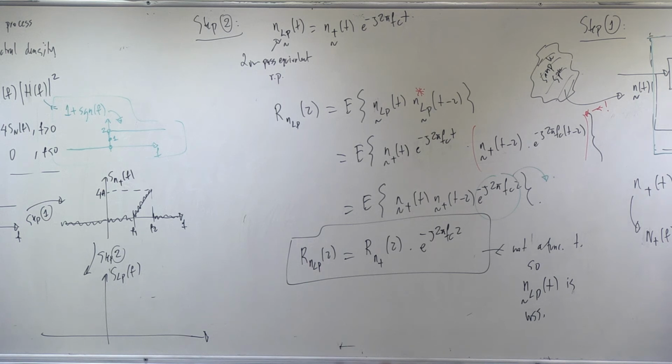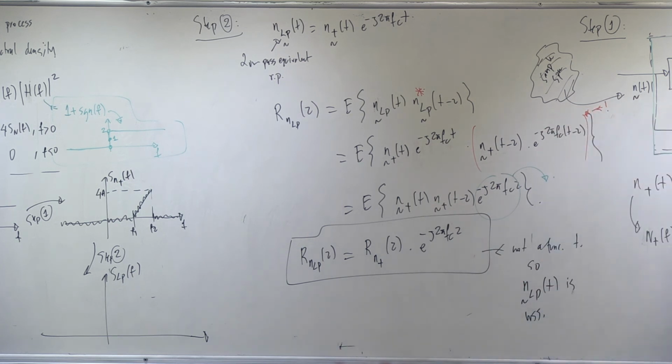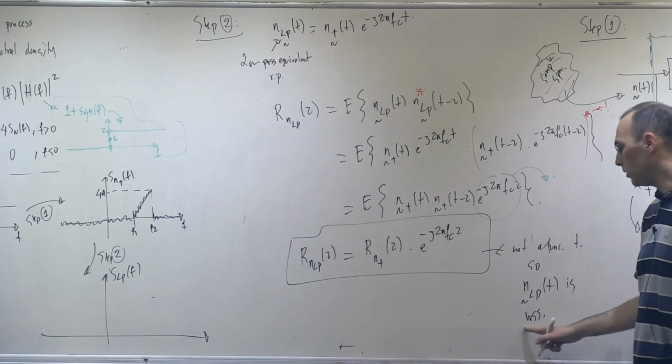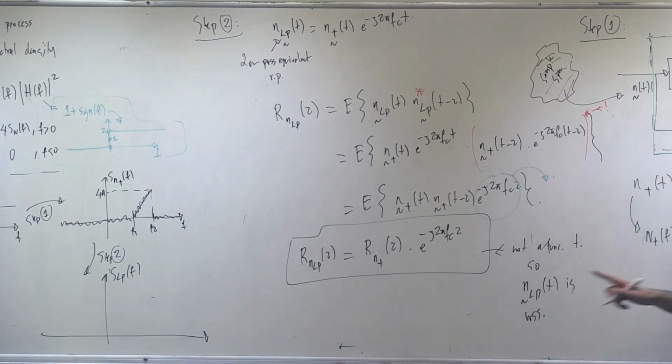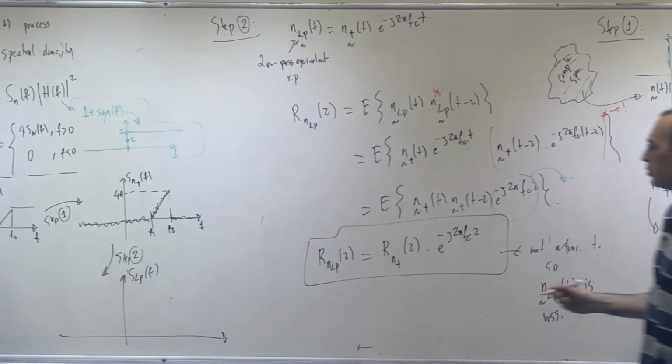So of course it is a zero mean process. Everything is zero mean. By doing these kinds of operations, everything remains zero mean. Okay. So zero mean, why do I need it? For wide-sense stationarity, I need stationarity in the mean and stationarity in the autocorrelation, as you see. Okay, so how about this?